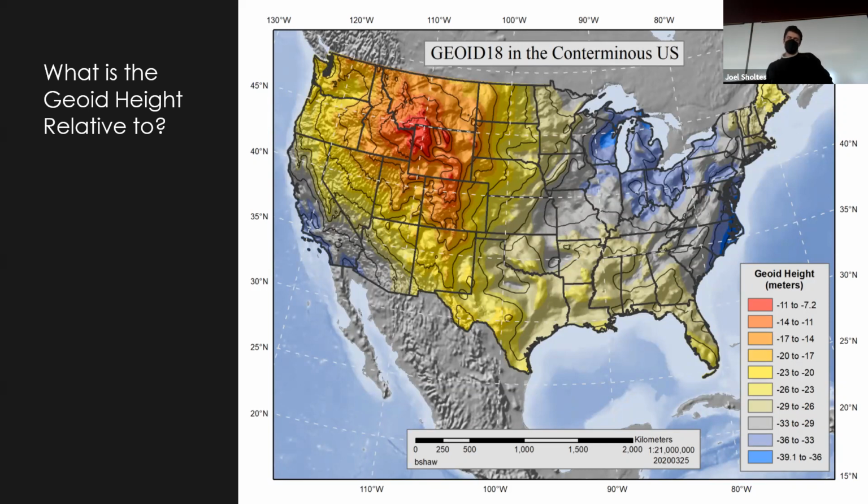Yeah, you would think it would be more dense. Oh yeah. So okay, because the Rocky Mountains are more dense, the geoid height is less negative, and so mean sea level is actually closer to the ellipsoid height. Where we have less dense material out here, a lot of sediment, right, alluvial stuff, glacial outwash, less dense. This is granite and really dense rock. So it's less dense, the geoid model falls farther below. I feel like I understand.